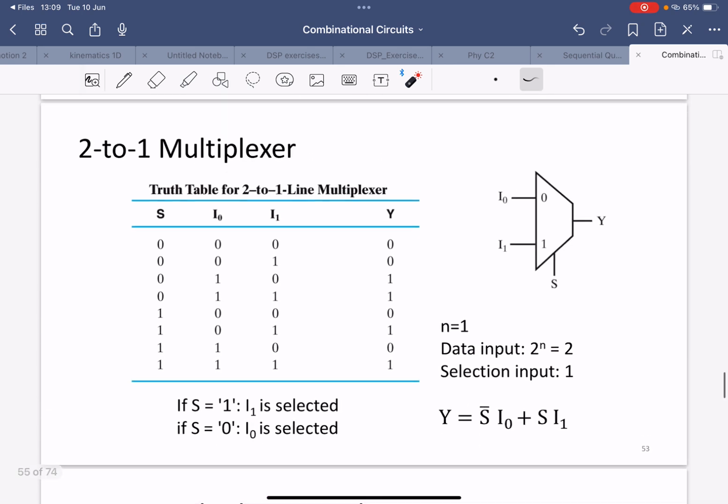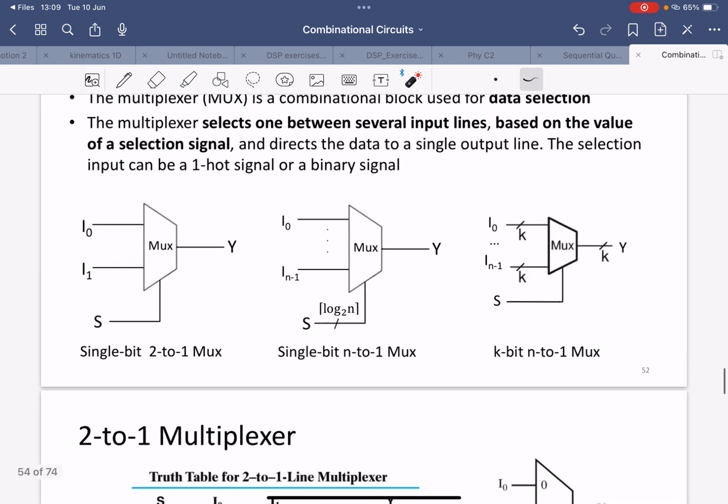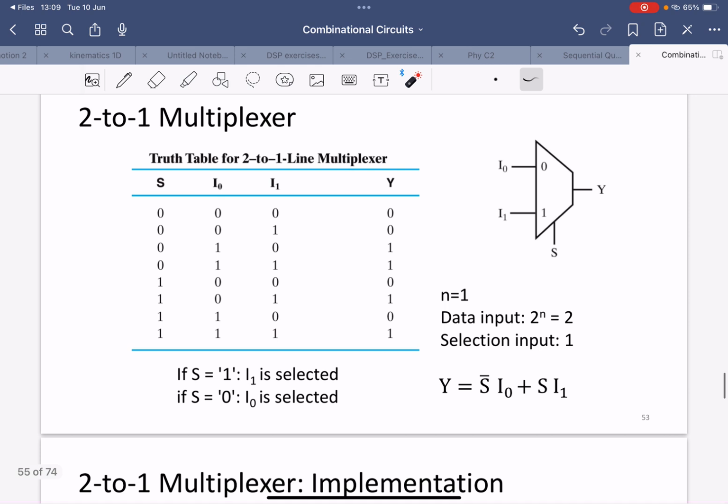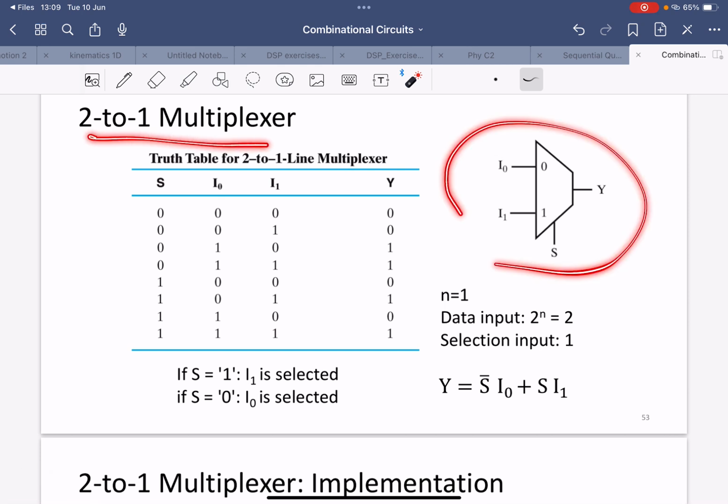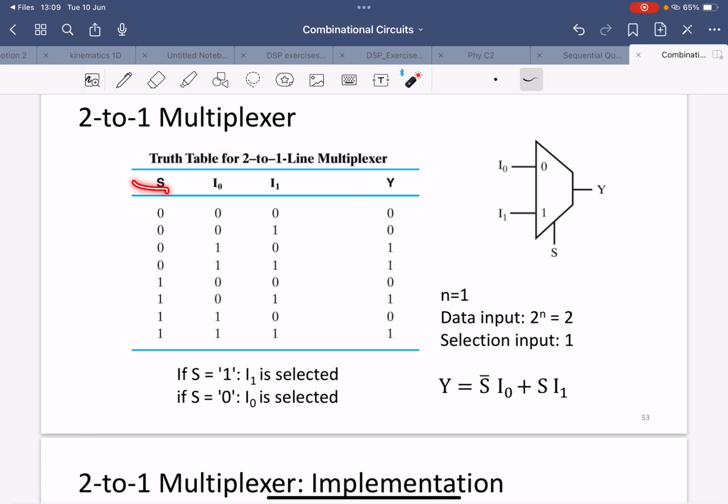Can we look at these ones? This one you cannot understand till this is the logic function. See, 2 to 1 multiplexer, this is a selector. When the selector is 0, and both inputs are 0, 0, the output will be 0. With 0, 0 and this one 1, the output is still 0. Why? Let me check.